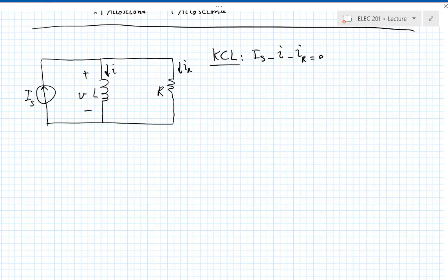You see, if I didn't have the resistor, the inductor would say, OK, I'll take the jump. My voltage will be momentarily infinity. But now, if V is to become infinity even for no time at 0, then the voltage across the resistor is the same, right, by KVL. So if the resistor has to have infinite voltage, what is the current in the resistor?